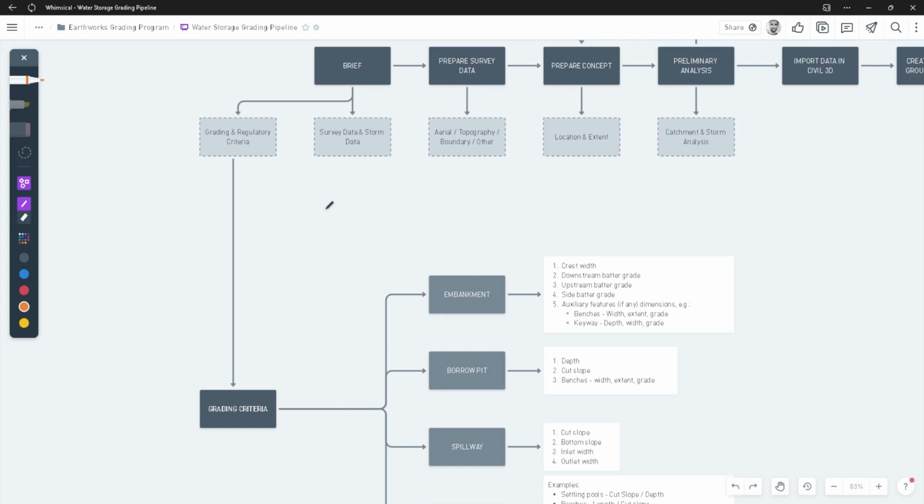And 1 meter per pixel resolution data is not very good even for this kind of work. Ideally, you would have something down to 0.1 to 0.25 meters per pixel resolution, and that's expensive. Anyway, you are able to find it, even if it's available from governments, or you may have to buy that, and it's not cheap. Even more if you have to prepare that data yourself or hire somebody to do it.